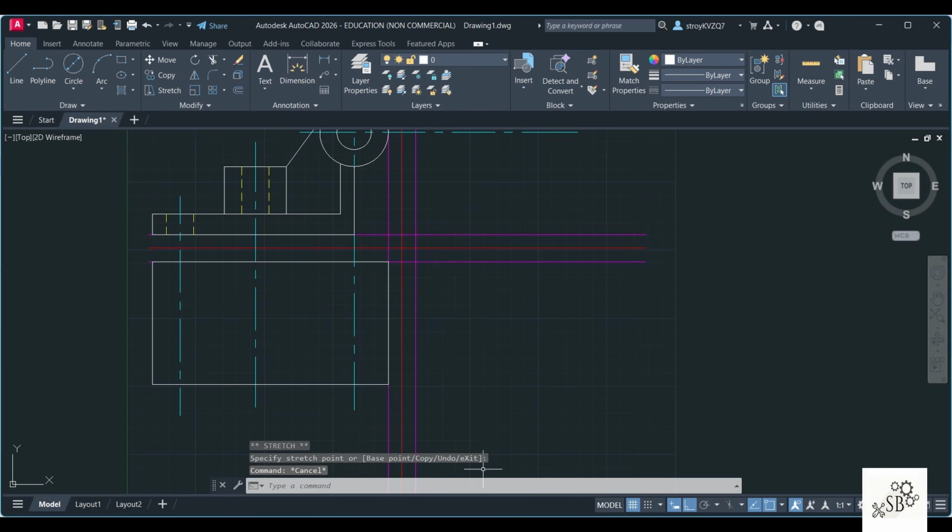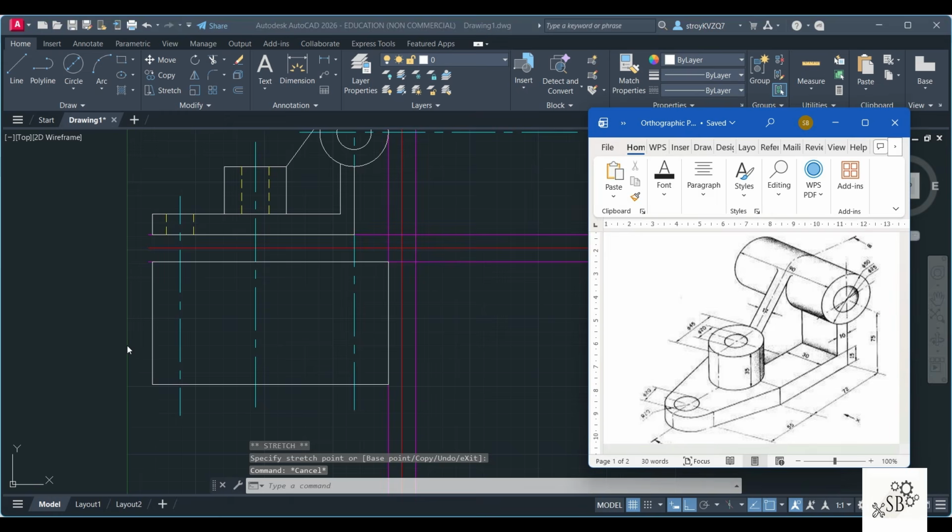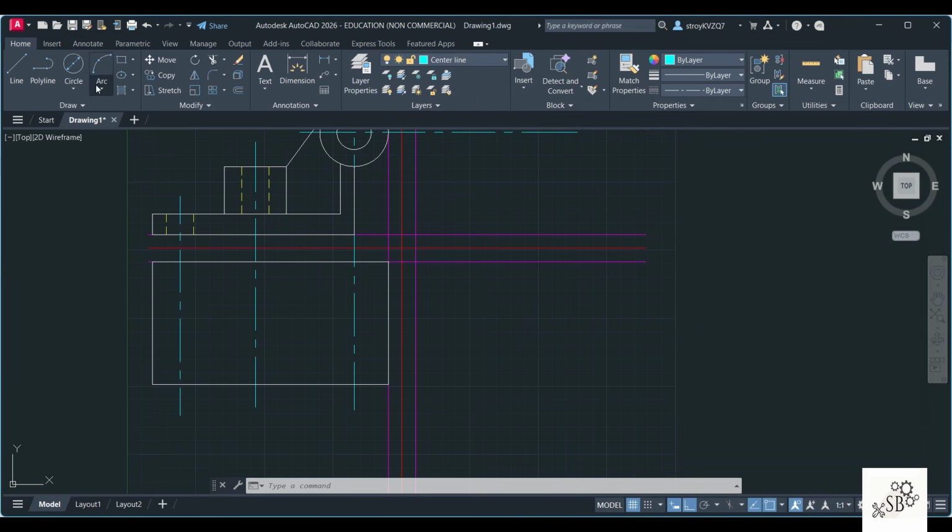Now, if I have to start drawing, I'll have to first observe where I want to start. So if I start with this circle and the semicircle here, this is exactly at the center of this entire object. So since this is 90, I will choose center line, choose line. From here, I will draw 45, half of 90, and I'll draw the center line. Escape. Just delete this portion because it is not required. Here now you get the intersecting portion.